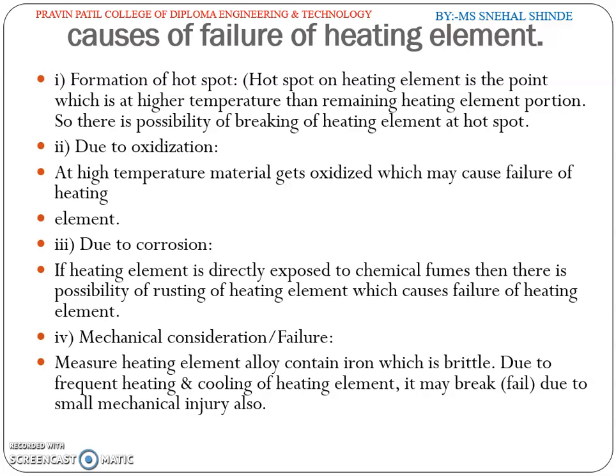Then mechanical consideration failure: the heating element alloy contains iron, which is brittle due to frequent heating and cooling of the heating element. It may break and fail due to a small mechanical injury also.